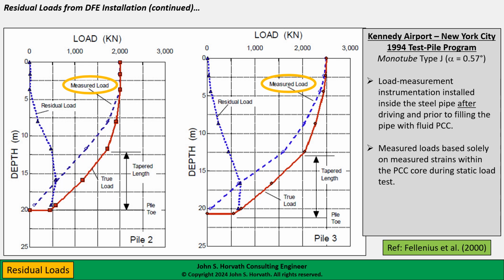But in any event, the measured load showed that these piles were carrying only friction, basically no toe load. And this sort of conclusion is not unique to these two piles. There are countless instrumented piles in the older literature where you see this behavior of little or no toe load, even in a coarse-grained soil such as this site. All friction, if you will, or mostly friction.